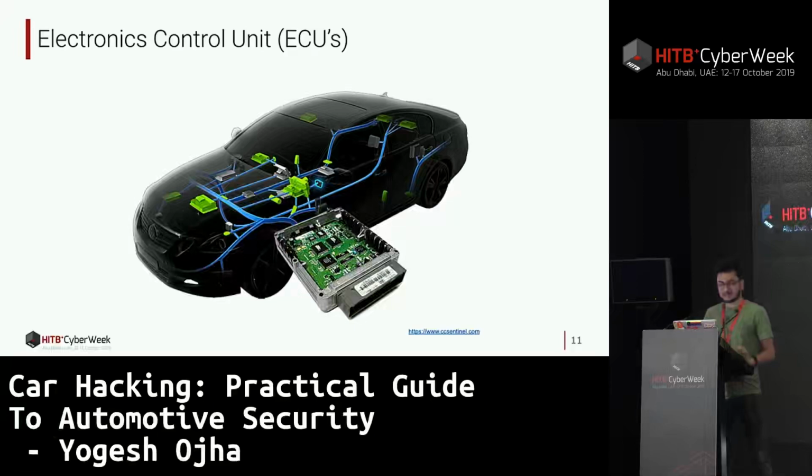An ECU is any controller that typically has a microcomputer inside it with a bunch of wires and peripherals, running a small algorithm in a closed loop and waiting for some input. Once the input is fed, it makes some decision based on that, and the output is actuating. It's an actuator, so mechanical components like moving a steering, engine combustion, to critical decisions like airbags, anti-braking systems, etc. These generally have something called a closed loop. This is a scheme that monitors the output of a car system and controls the input. So it's not going to take any input that is not intended for it.